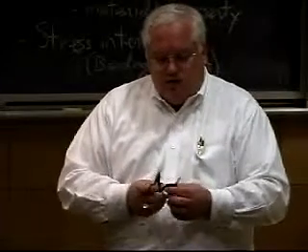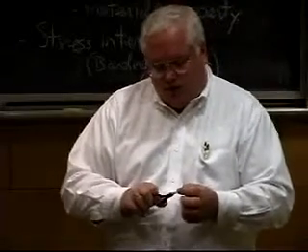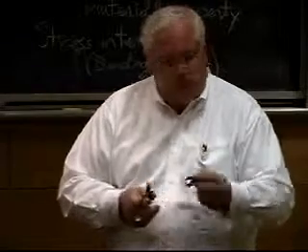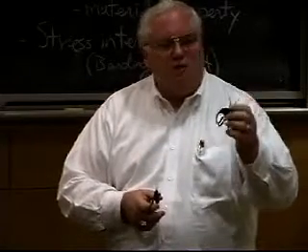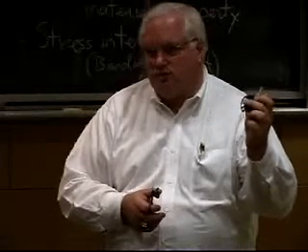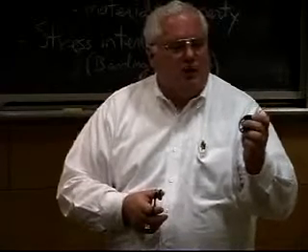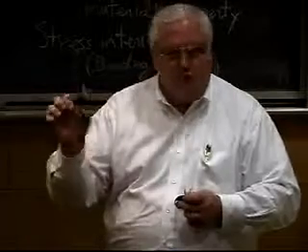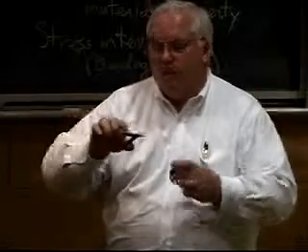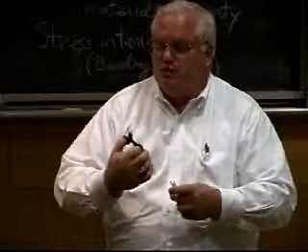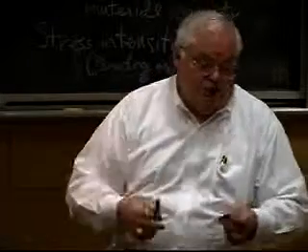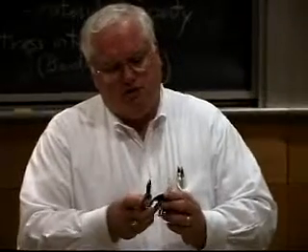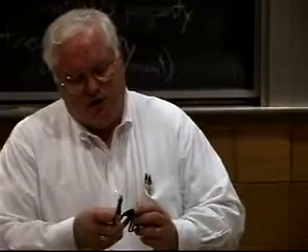So here's some Japanese scissors made out of ceramics, basically aluminum oxide. That's why it's a white ceramic. The wonderful thing about ceramics is they're so hard that they'll stay sharp for a long period of time. That is, unless they chip, which if you look carefully at both of these, you'll see chips. And at that point, they're very difficult to sharpen. This one, you can actually feel some chips. If you close it carefully, you can feel some rough spots.